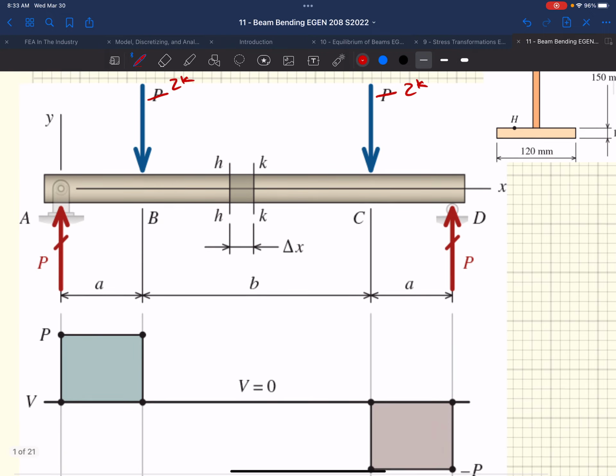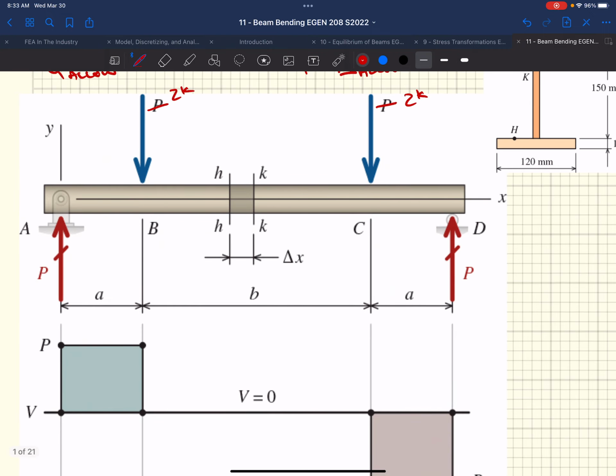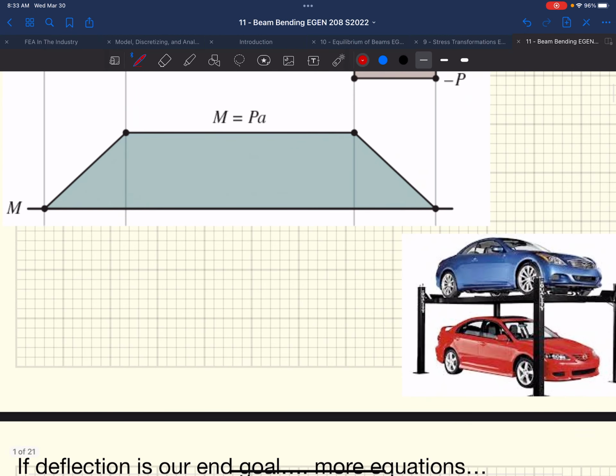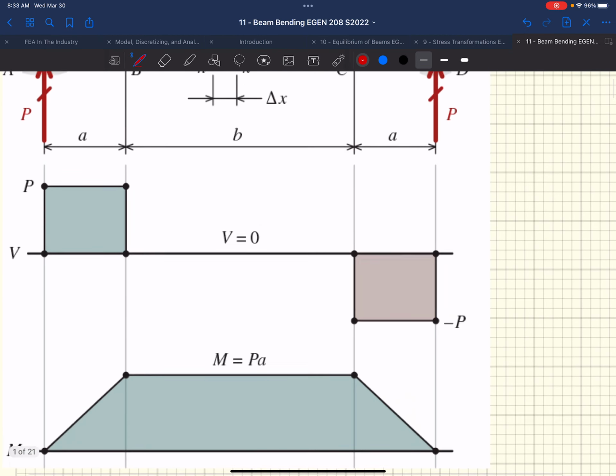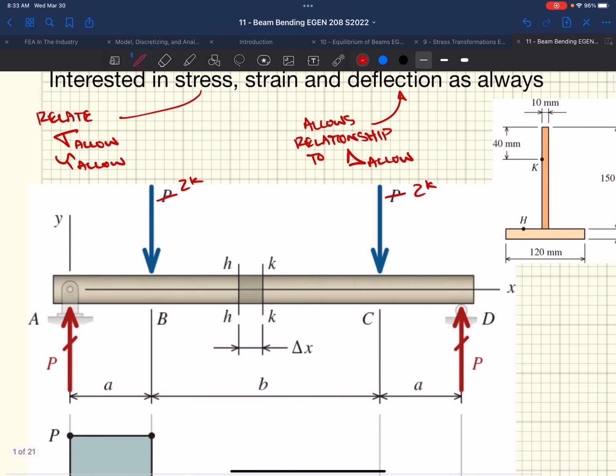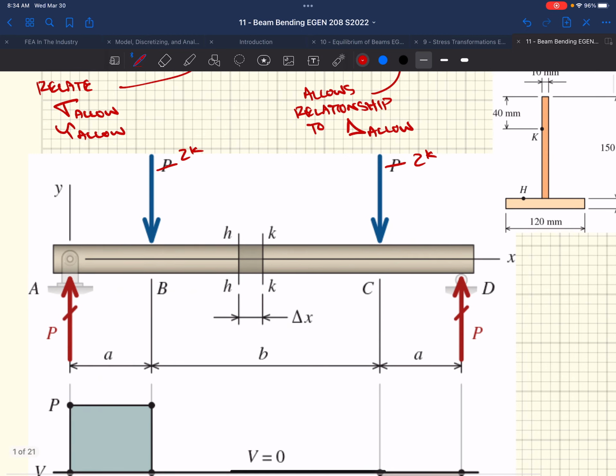All right, so if we had a car, say it weighed 8,000 pounds, so it's definitely not this car right here. It might be a 1-ton pickup, okay? 8,000 pounds. We're going to have 2 kips at each one of our 4 tires. We're going to put these 2 tires on our beam. Based on symmetry, I think we could all agree that we are going to end up with 2 kips of reaction at each side if we summed the forces, or the moments.